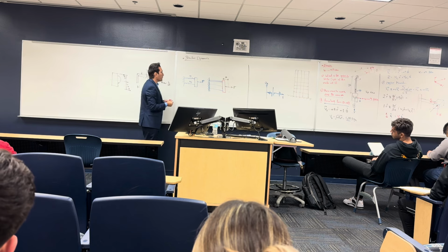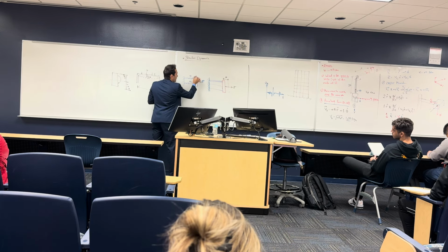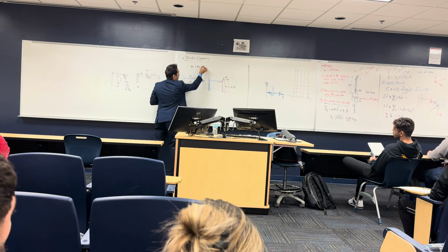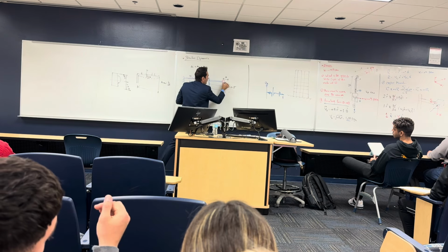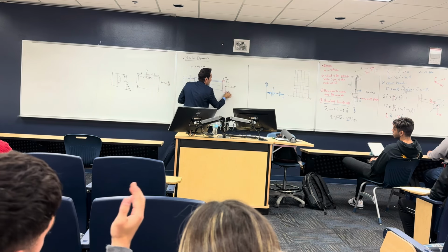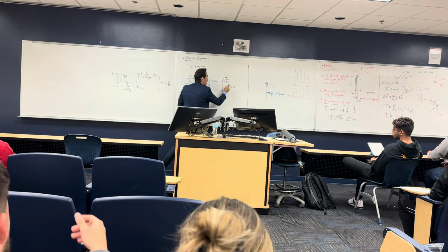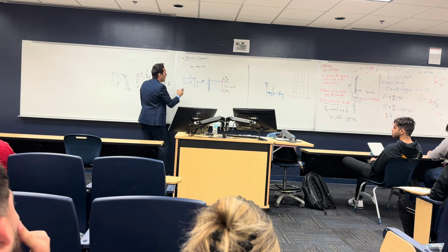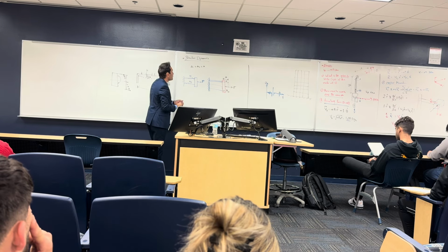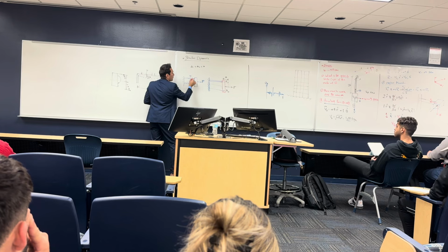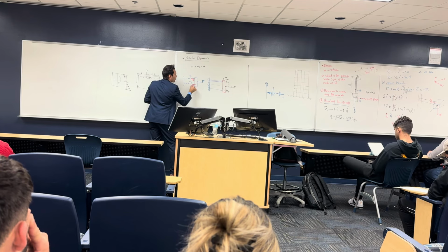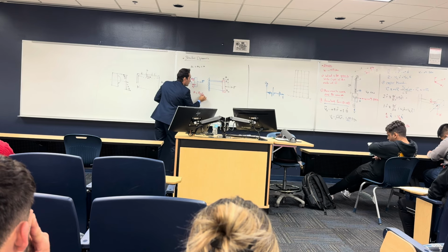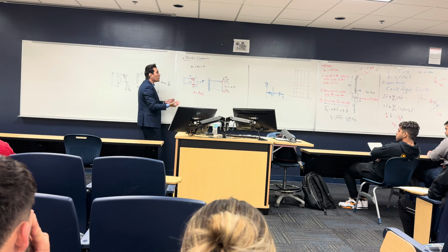If the springs are in parallel, delta 1 for spring number 1 is equal to delta 2, which is equal to delta. Both springs are going to move, this is delta 1, and this is delta 2. And delta 2 is equal to delta 1, which is equal to the delta of the system, okay? But spring number 1 is going to absorb a force F1, different from spring 2's F2, but F is equal to F1 plus F2, the final F, okay? Who is going to take more force?